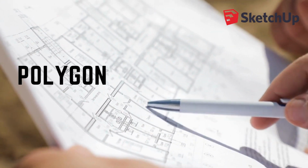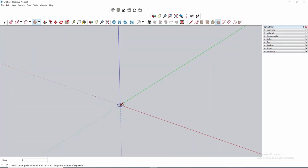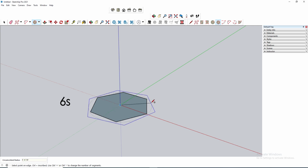Polygon. When you first activate polygon, before clicking any points, you'll see the number of sides listed in the sides box, located by default below the SketchUp window. If you want a different number of sides, type the number and press enter.